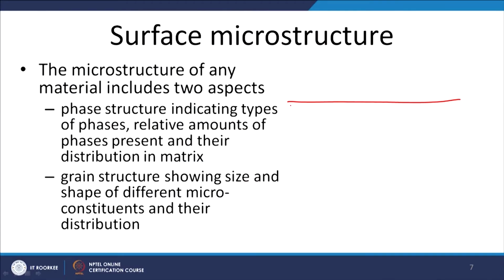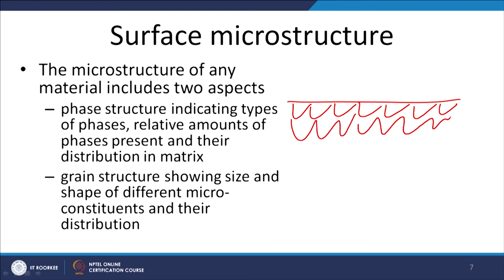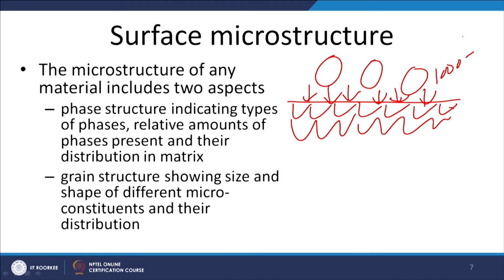Similarly, under cavitation conditions, whatever surface layers are there will have their own structure, but whenever there are cavitation conditions, bubbles burst, and bursting of the bubbles generates pressure waves or shock waves, which build up high pressure, which can range from 1000 to 1500 MPa. Such high levels of stress will be leading to near surface layer deformation.